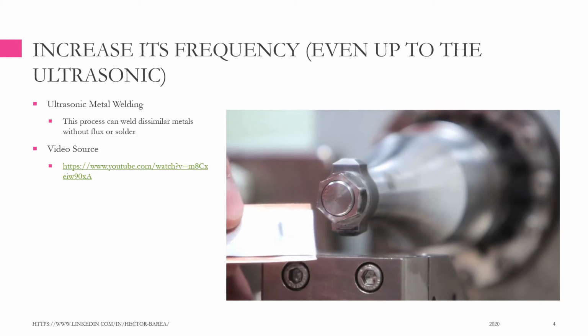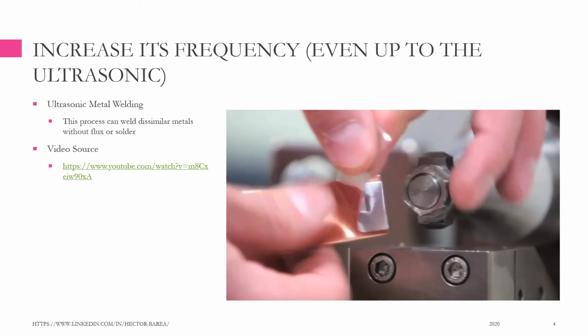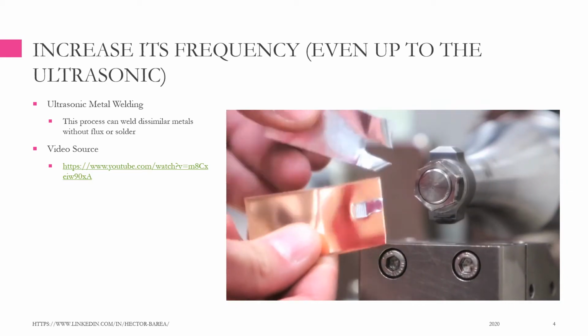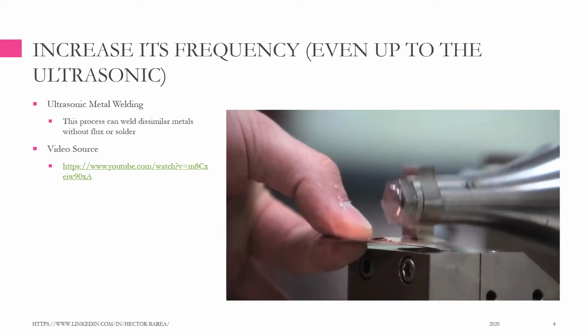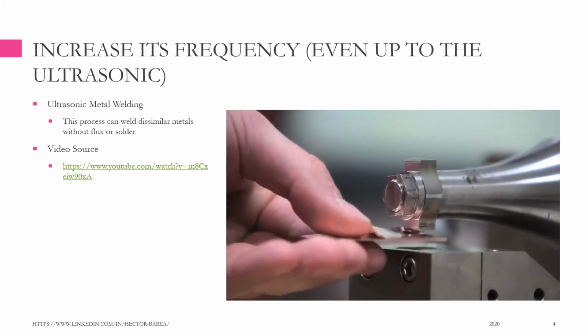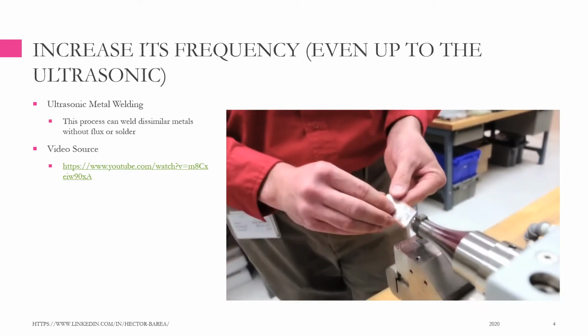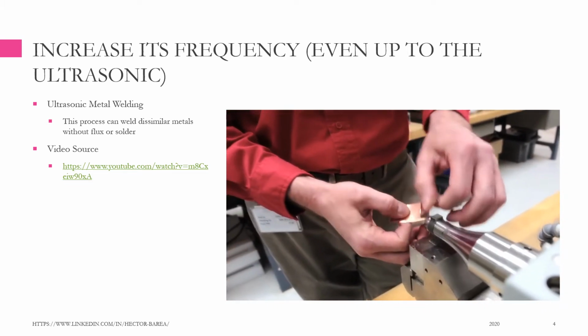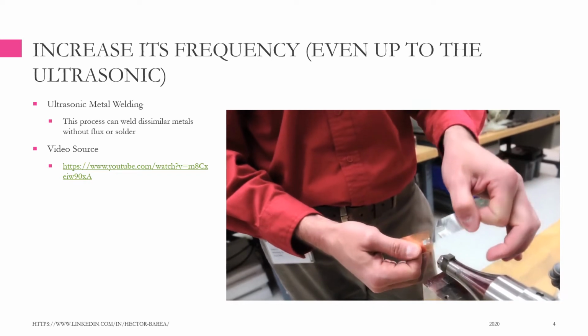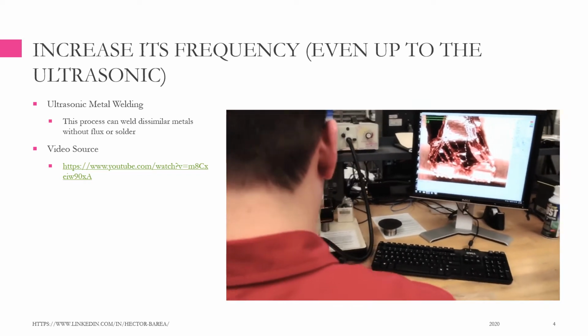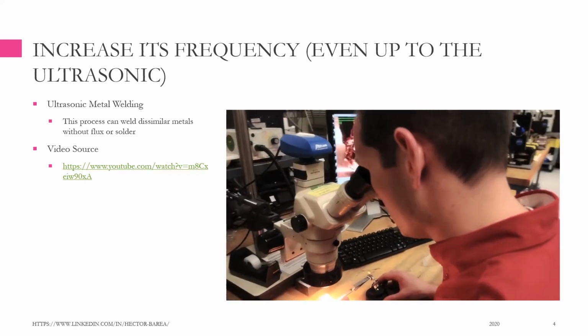Ultrasonic metal welding can be used with copper, aluminum, nickel, and magnesium, and cycle times are typically less than a half second. This process works well with materials that have high thermal conductivity, for the multi-layer thin foil welds common in battery applications, for structural aluminum joints, and for consumer electronics and medical devices.